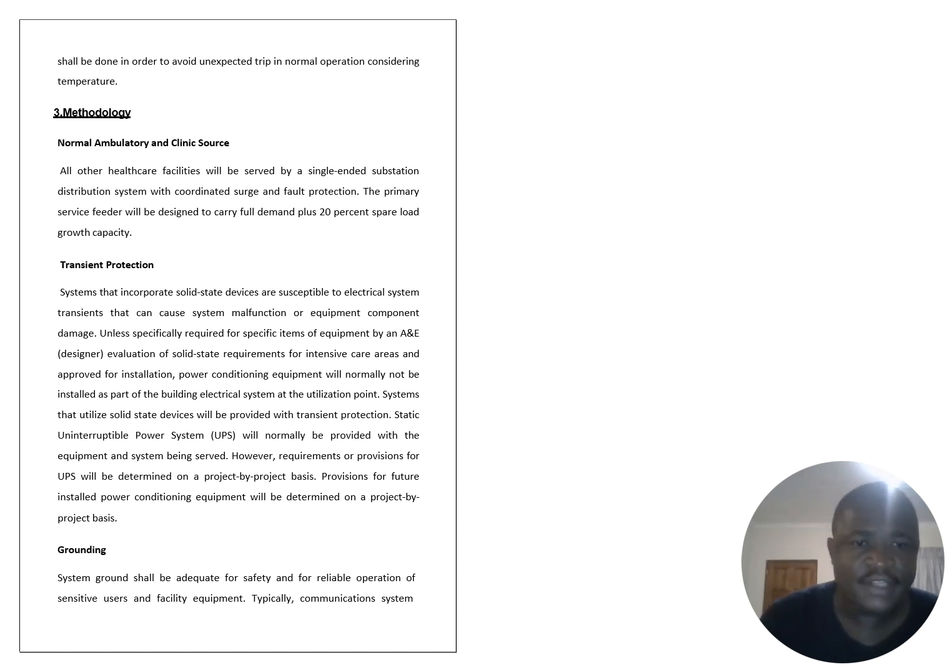All healthcare facilities will be served by single-ended substation distribution, and there will be coordinated surge and fault protection in the primary services, designed for full demand plus a percentage payload. Transient protection systems will incorporate solid-state devices and subsystems to handle internal system transients that can cause malfunction or equipment component damage.